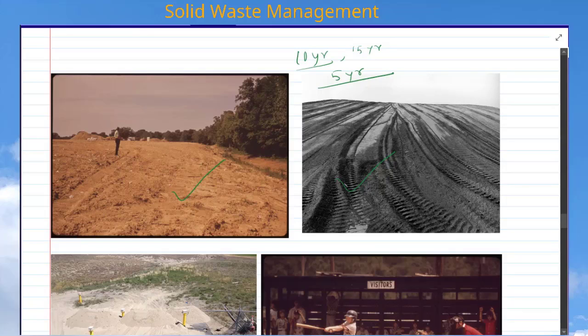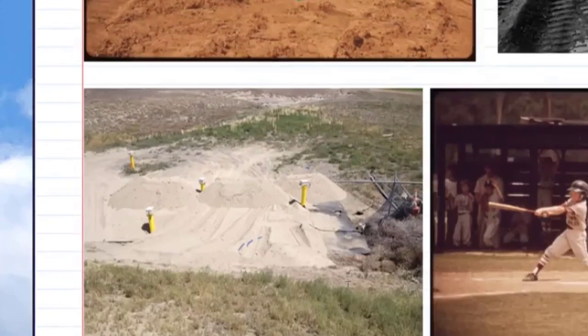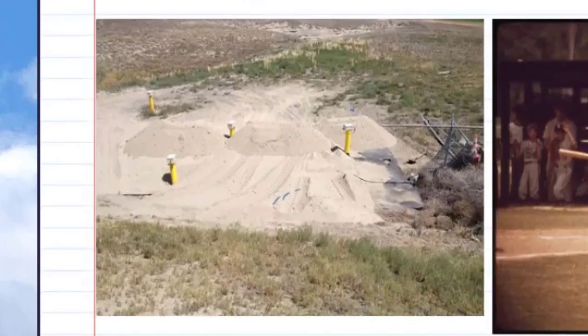If the landfill area is quite large, the site can be used for 10 to 15 years. At the end of this period, the whole disposal site is covered with impermeable soil material or clay, and generally there are some vent pipes, so that the gas produced by degradation beneath the soil can escape from the space.